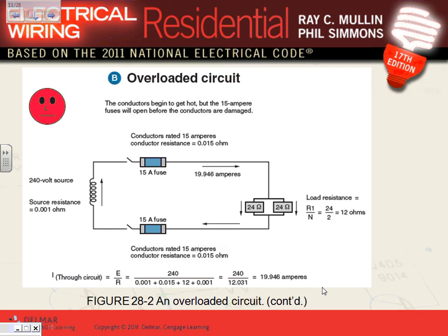Look what happened then. If you remember, if you put two loads in parallel, what happened to the overall impedance of the two loads? It's cut by half if it's the same. So look at the R, that 24 ohms became 12 ohms. When you have two loads, if I take the city of Bloomington and clone it and tie the two cities of Bloomington to the grid, the overall impedance will go down, because that's the beauty of the parallel circuit. Every time you add a load in parallel, the overall impedance of the system goes down.